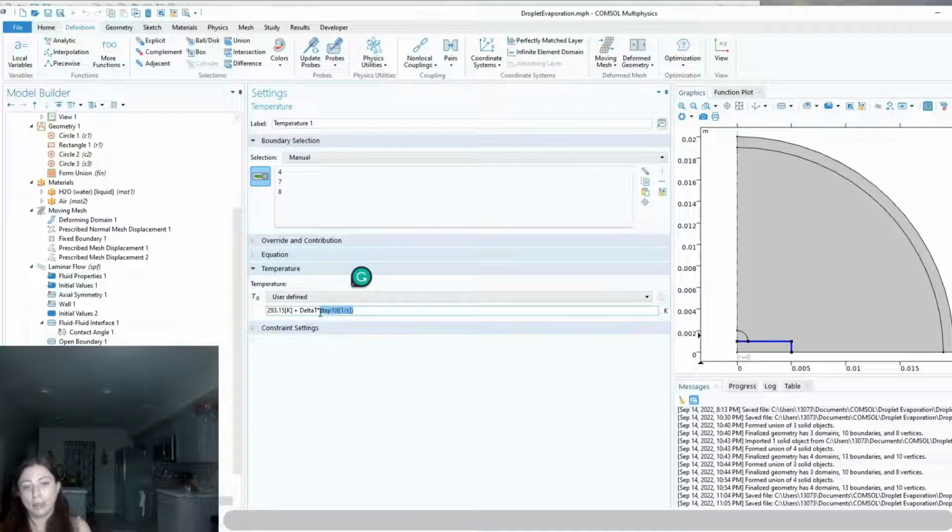So why do we need this step here? Because we've got a delta T here, so if we didn't have a starting time 0 for the solver, it would run into singularities, I guess you would call it, where it can't solve. So you have to give it at least a fraction of a second to have a base time to then calculate delta T for all times after that. So we just use a turn on function with smoothing, so it has a time 0 to start with.